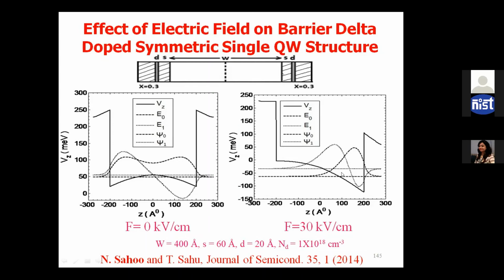So now the distance increases because there are positive ions, and the electron is distributed at this edge. As the distance increases, R increases. As R increases, the Coulombic force F decreases. So the ionized impurity scattering can be reduced. It can improve the mobility.